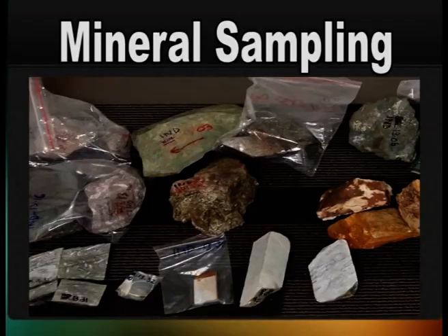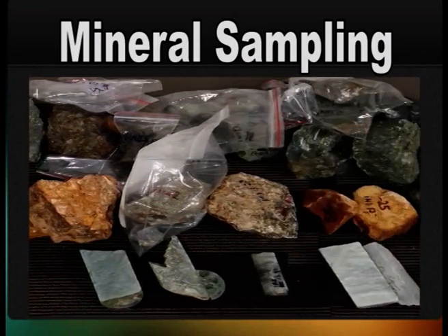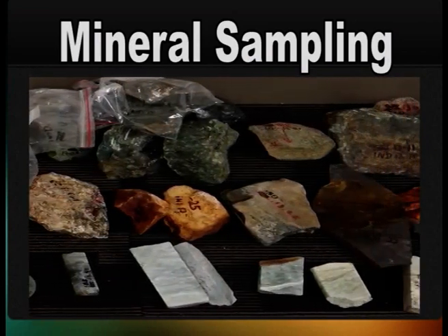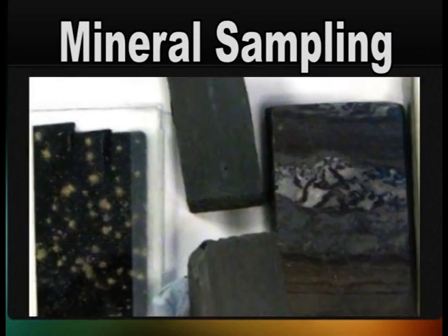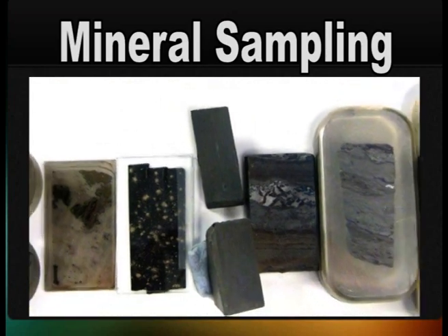Mineral sample preparation is a vital stage in the process of mineral analytical testing. The purpose of sample preparation is generally the production of a homogeneous subsample representative of the material submitted to the laboratory. Correct preparation is critical to obtaining meaningful analytical results. The selection of the specific sample preparation procedures will depend on the type and size of the sample, the mineralogy, as well as the client's analytical and budgetary requirements.